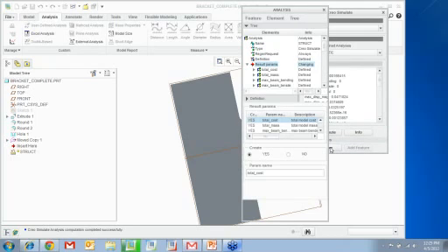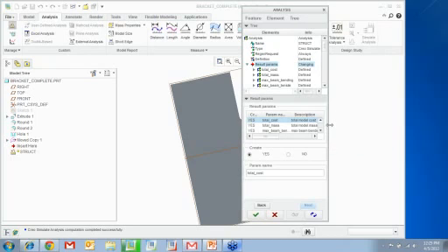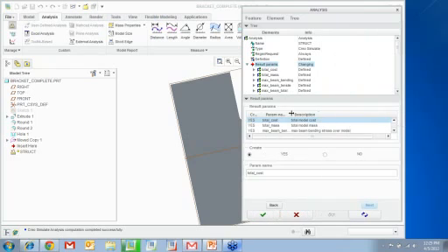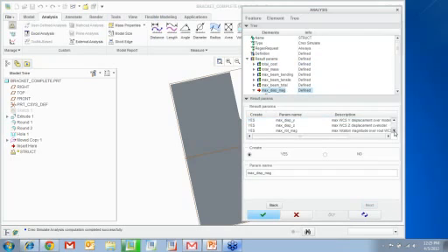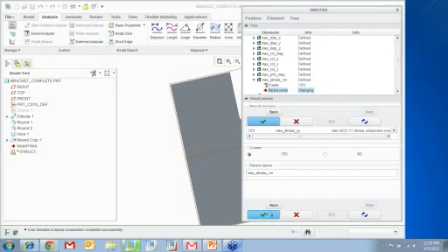Close this. So notice that it's going to ask you to create a parameter for these things. So you can see you have total cost, total mass, maximum displacement right here, maximum one meter stress. You can choose to change the name over here to whatever you want. All right. So it's creating a parameter for that. I'm going to say done.